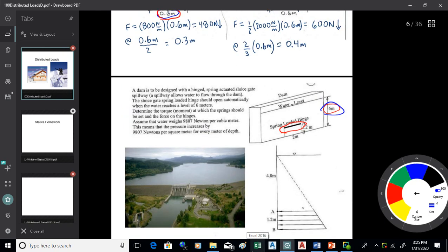You need somewhere for the water to go. There's obviously a river up there at the head of that reservoir, and it's putting water into the reservoir, so you have to let the water out. That's done through what's called a spillway. A spillway is just a way to let the water over the dam in a controlled way so it doesn't do any damage to the dam. You don't want just water running over the top. That's going to be problems there.